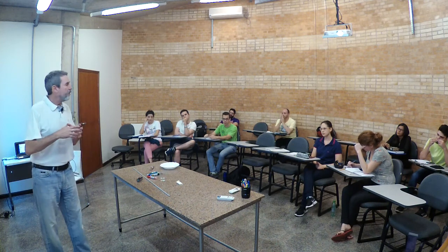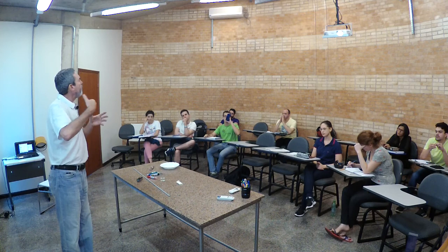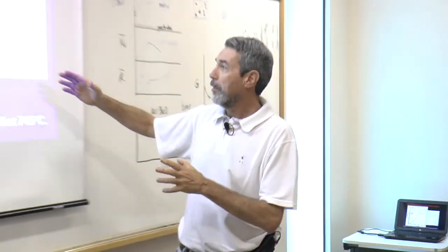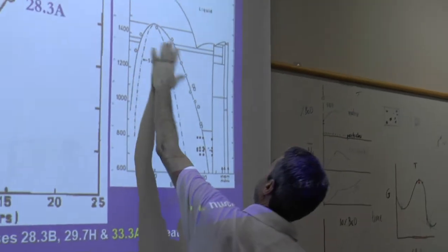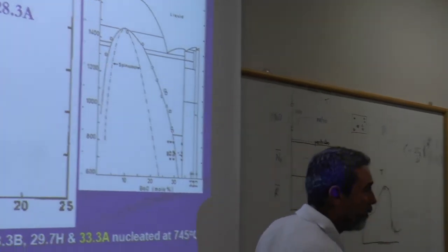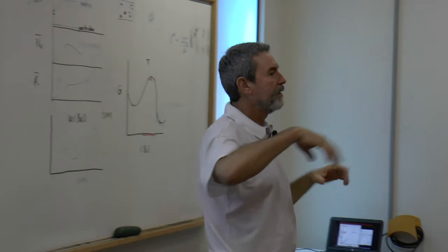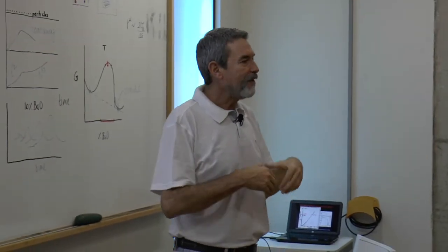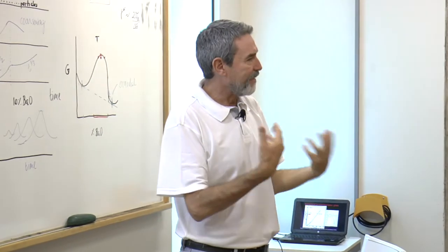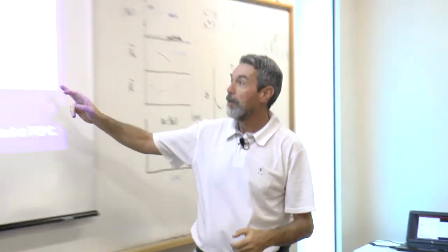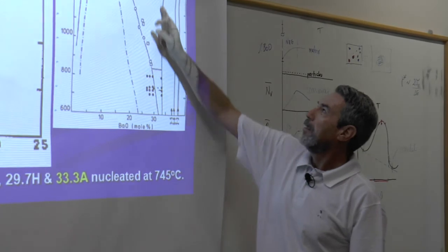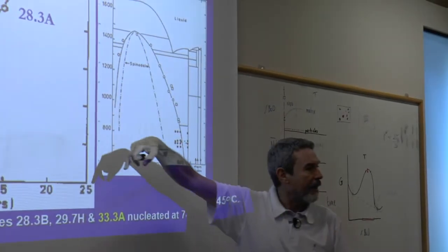Yes, because the crystalline phases are dictated by the phase equilibrium diagram. So the phase equilibrium diagram does not see this binodal and spinodal boundary. They're not seen by the crystals. The crystal phases, the equilibrium phases, only see the equilibrium diagram.